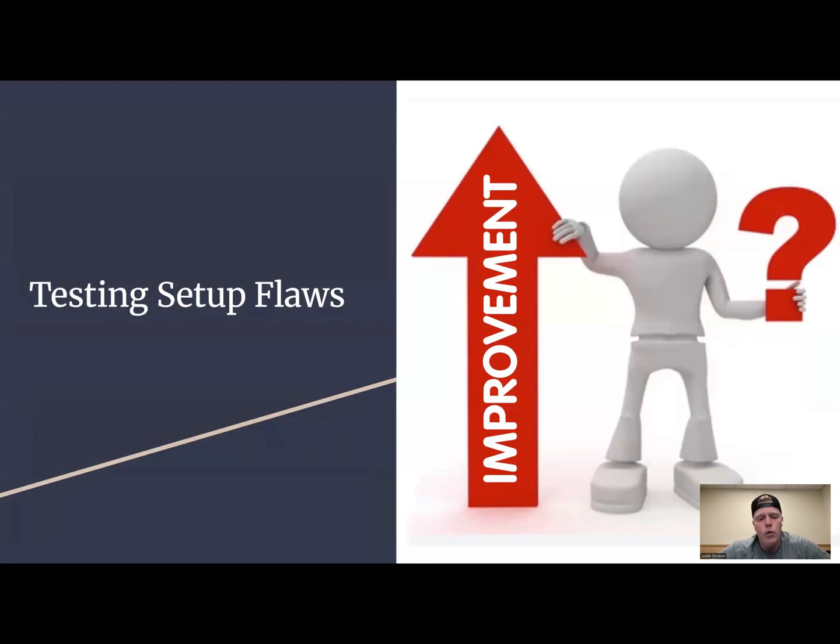Testing setup flaws: we only tested one L beam and one straight beam. This can lead to some errors from not every beam being the same. We did run a few trials. However, we realized later that we were likely in the plastic deformation loading phase of the bar, ever so slightly. So that could lead to some errors with differing modulus of elasticity, and vice versa. Varying things can happen from that.